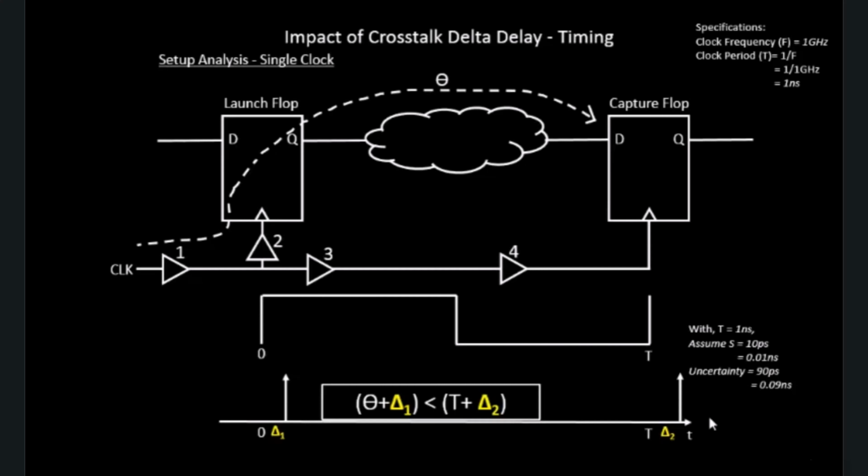It's like a road. A road is never flat, it has some pebbles, some speed breakers, so you can't predict the time required to move from one end of the road to the other. It might vary for 2 different roads. Similarly, the clock signal itself will have varying paths. The time required for the clock edge to reach this capture flop will be different from the time required for the same clock edge to reach a flop sitting at this corner of the chip, because of some variations.